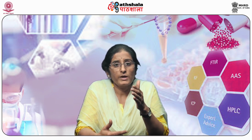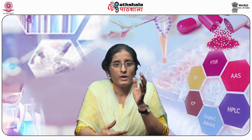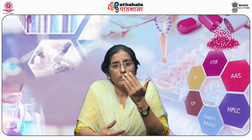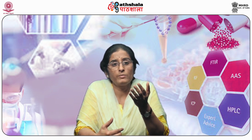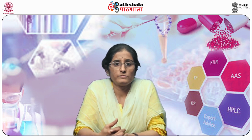The mechanical property of the plastic can be altered by some solvent systems. Examples: oils show a softening effect on polyethylenes. Polyethylenes and polyvinyl chloride are attacked by fluorinated hydrocarbons. So one should be quite careful what type of material he is storing in the plastic packaging material.